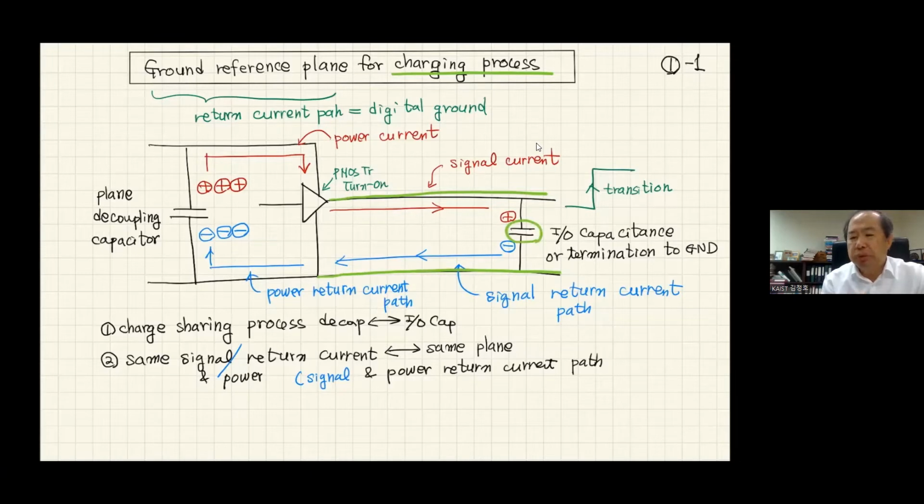Of course, we also have inductance and resistance, but at this moment, we are assuming that we are only concentrating on the case where the I/O interconnection can be modeled as a capacitance. Those cases could be true when the interconnection line length is very small, but a general understanding of the return current path at this moment will be okay for this capacitive loading.